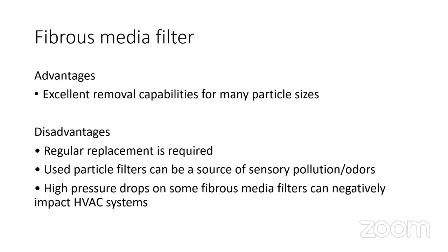as the load increases, the removal efficiency, when it gets deposited with more amount of this, the pores close down, and then the removal efficiency is reduced, and then at that point of time we need replacement of the filter. Then used particle filters are again, because these contaminants get deposited on that, a source of sensory pollution or odors.